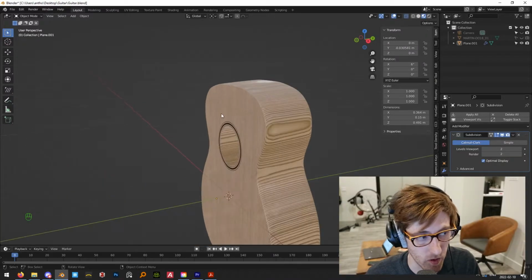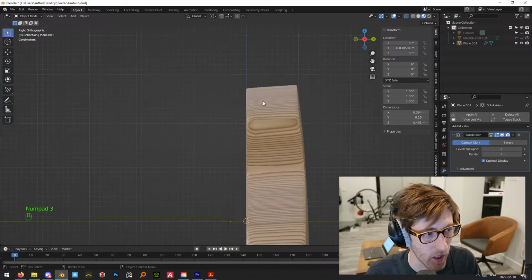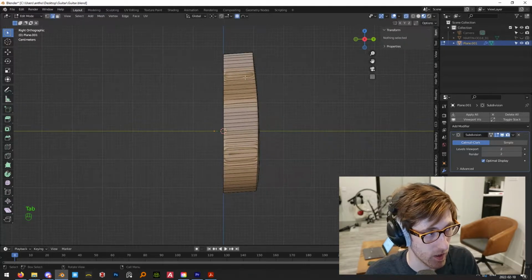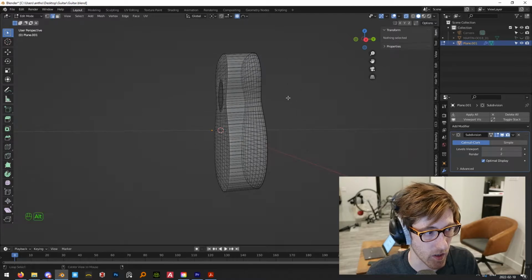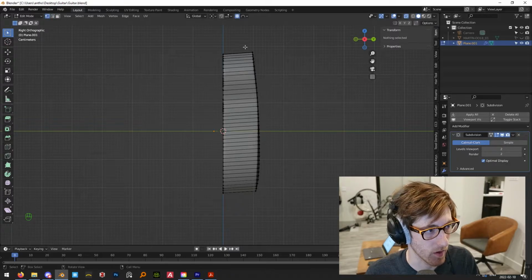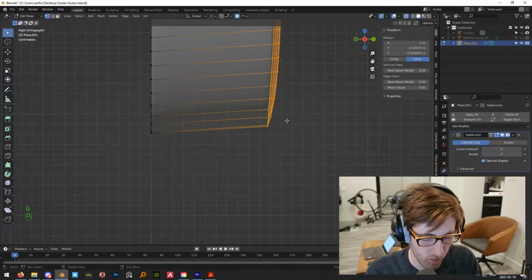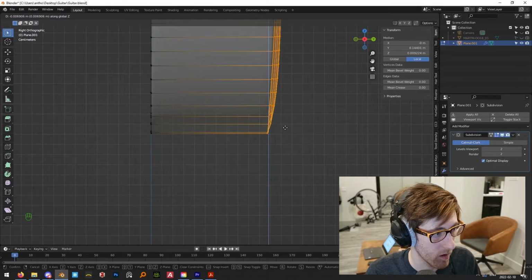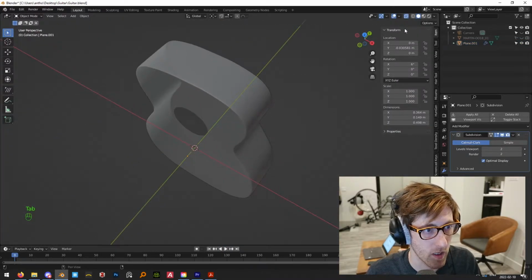So now a couple of things quickly first. Depending on the way that you rounded the back of your object here, you might find that it's sort of raised up a little bit. And so if we just tab into edit mode and go to viewport shading and just make sure that we have X-ray mode turned on, which is Alt Z, and then go into vertex mode. I'm just gonna select this entire back and just hit GZ, turn off proportional edit with O, and GZ to drag this down so that this is once again lined up correctly with the front.